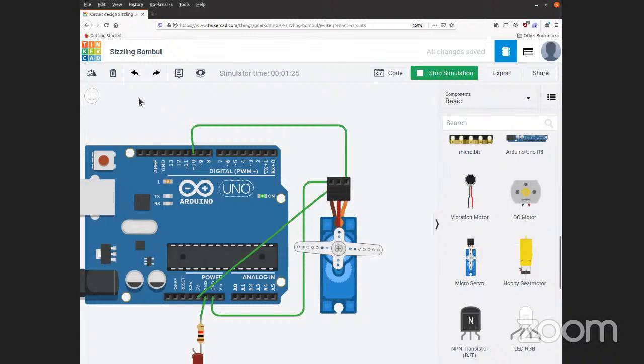And to prevent stuff like this from happening, you have to make sure that you're not doing too many intense calculations, like multiplication or addition using floats or doubles anywhere in your program. So if you ever see a float or a double pop up in your program because that was an input from a sensor or something like that, just immediately convert it to an int, unless it's for printing to serial. All right, now that's out of the way. That's the end of this workshop.